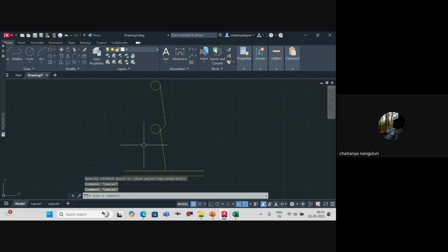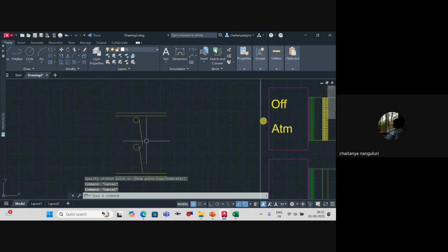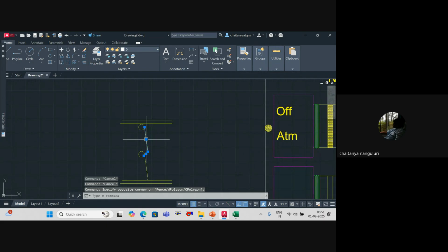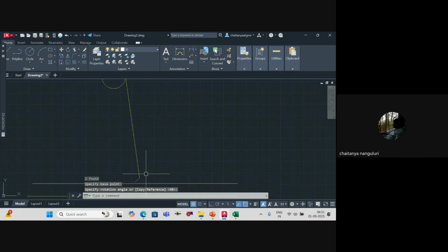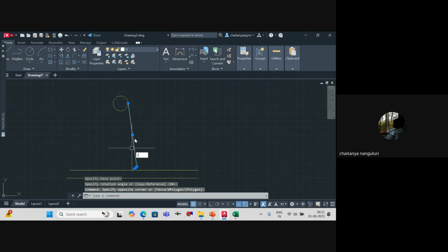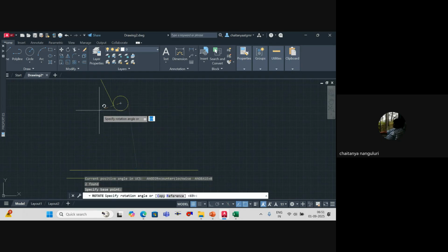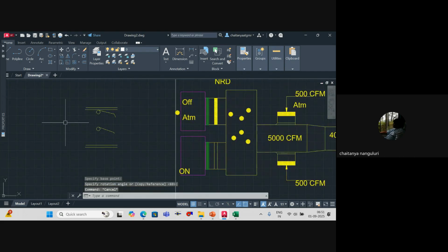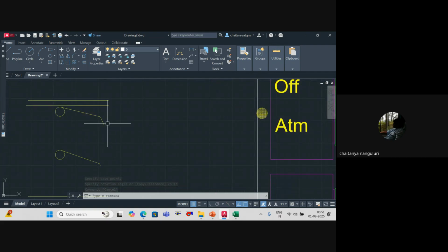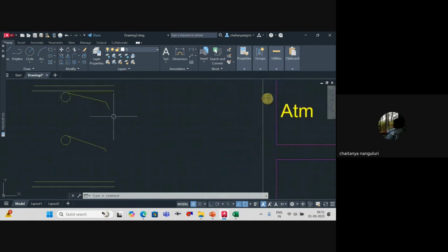Whenever the air is flowing, it will be made of light material. Because of this hinge, this will rotate at this angle. This will open like this, and obviously the bottom one will open. So air will flow when air is pushing in this direction. But if it comes in this direction, because of this bevel angle, it will be in a closed state.